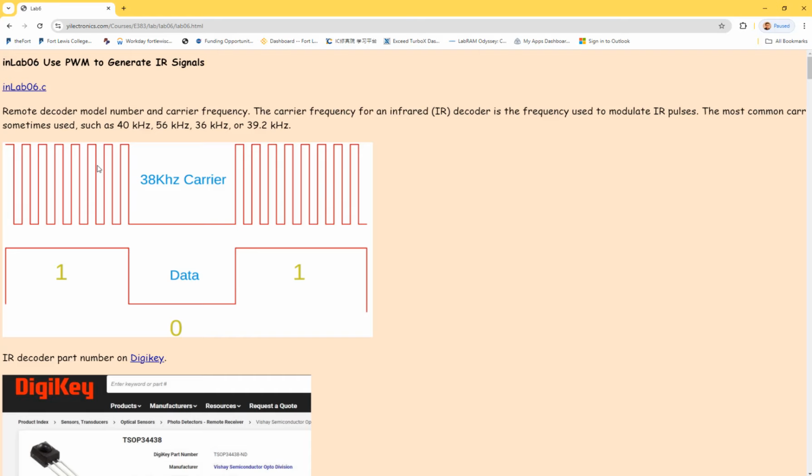You have to send electrical pulses from your microcontroller, electrical voltages, to the LED controlled by the transistor, and that's going to convert that pulse into optical pulses. It's going to be photons, sent through the air and received by the decoder, and the decoder is going to output this 101. Everything after this is on the board electrically, nothing in the air anymore. Make sense?